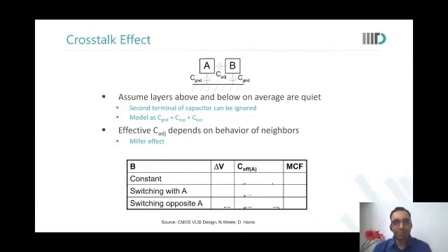Yeah, so in this pi or T model, when we have very long wires, then this may be true. But when we have wires which branch too much, then maybe this model will fail because there are parallel paths. So actually, it is for global signals that we use these pi and T models. For small interconnects, the resistances and capacitances are small enough that whatever they are, it makes no difference. See, if the overall value of the delay is 10 picoseconds, whether you're measuring it accurately at 9.7 picoseconds or at 8 picoseconds, 2 picoseconds is the inaccuracy of your simulator. Doesn't matter. So if the delays that could be impacted are within the accuracy of your simulator or your simulation setup, you don't bother about making pi and T models.